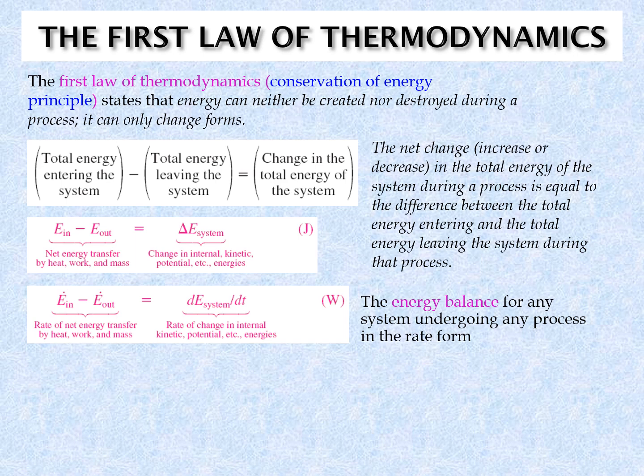The first law of thermodynamics. So basically, we already know that all things follow this thermodynamic law. All energy forms follow the thermodynamic law, which is that energy cannot be created nor destroyed. It can only change form. Okay, so from this first law of thermodynamics, we can write the energy balance equation, which is the total energy entering the system minus the total energy leaving the system should equal the change of energy in the system.